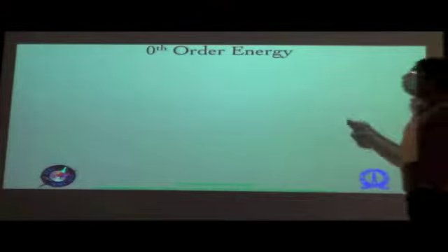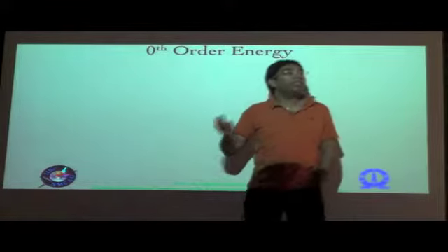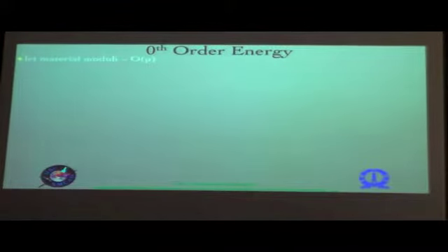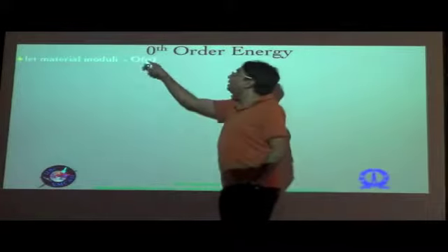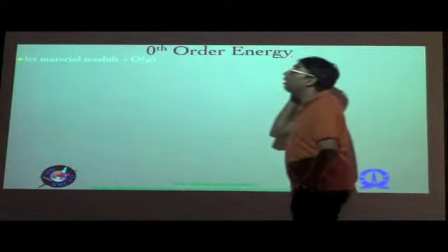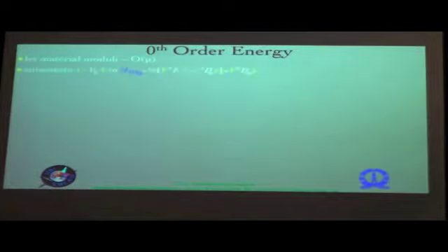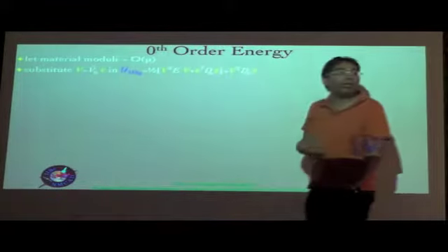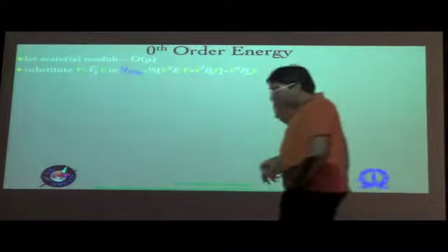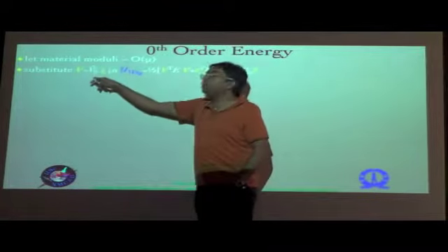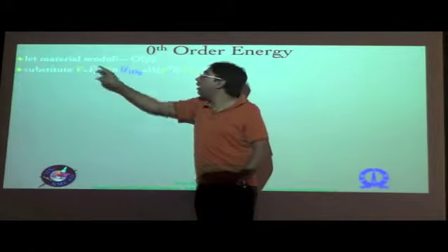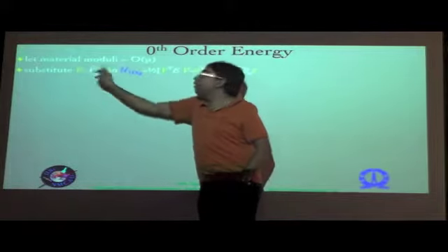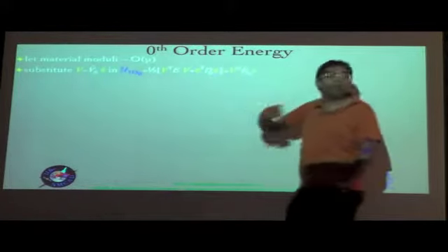So now we can use that solution to substitute into the 3D strains and back into the energy to get an expression for the 0th order energy. Suppose we call what we called E earlier, the material moduli, as order of magnitude mu, they are both the same. Substitute the expression we got for V as V naught hat times epsilon bar, where in the actual numerical problem we would have the actual numerical values of this n by 4 matrix, multiplied by the 4 by 1 to get your n by 1.